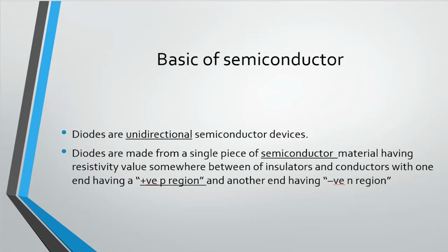See, unlike resistors, which are one of the most basic passive components we know in any circuit, the signal diode is the most basic active component. A diode does not behave linearly with respect to the applied voltage, as it has an exponential IV relationship and therefore cannot be described simply by using Ohm's law as we do for resistance.